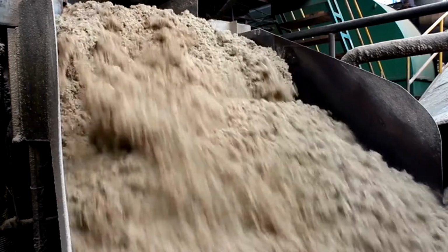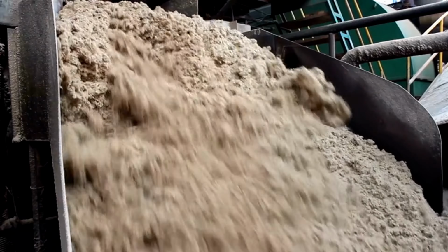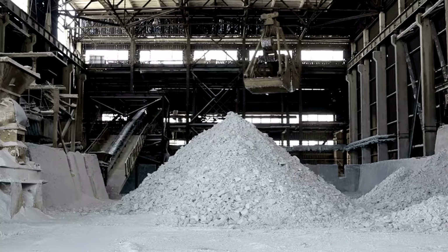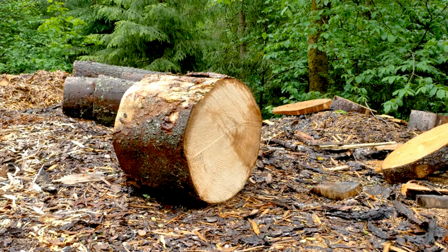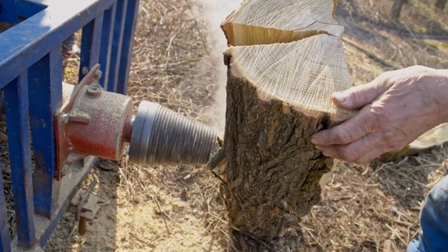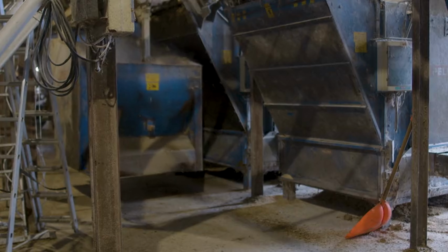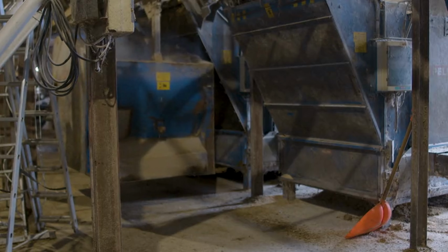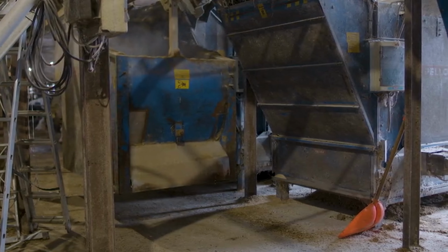1. Raw material preparation. The primary raw materials for paper making are wood, recycled paper, and non-wood fibers such as bamboo, straw, or cotton. Wood preparation. Log debarking. Logs are stripped of their bark using mechanical debarking drums or high-pressure water jets. Chipping. The debarked logs are cut into small wood chips, typically 1 to 2 centimeters, to ensure uniform pulping. Chip screening and storage. The chips are screened to remove oversized or undersized pieces before being sent to storage silos.